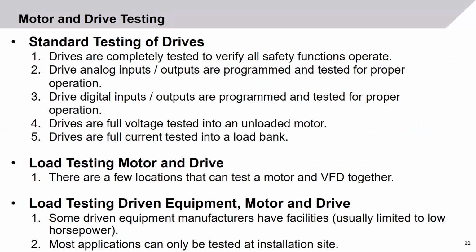Motor and drive testing, standard testing of drives. Drives are completely tested to verify all safety functions operate properly. Drive analog inputs and analog outputs are programmed and tested for proper operation. Drive digital inputs and outputs are programmed and tested for proper operation.